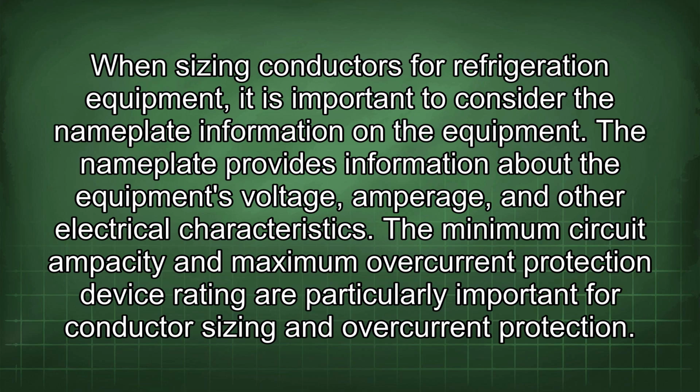The nameplate provides information about the equipment's voltage, amperage, and other electrical characteristics. The minimum circuit ampacity and maximum overcurrent protection device rating are particularly important for conductor sizing and overcurrent protection.